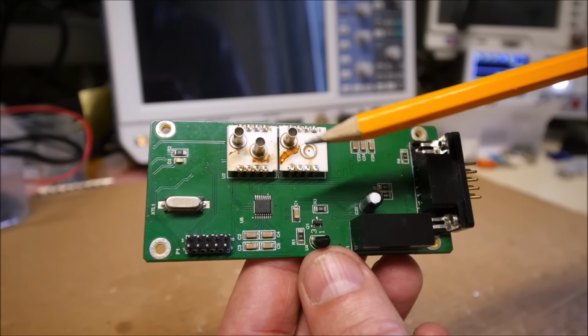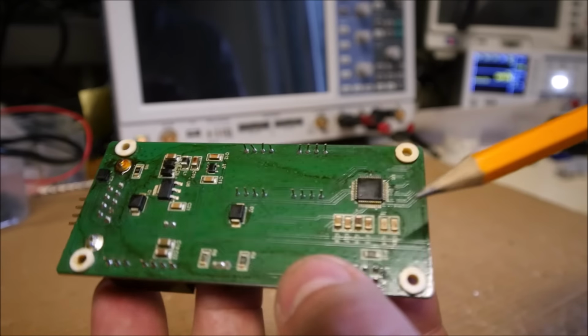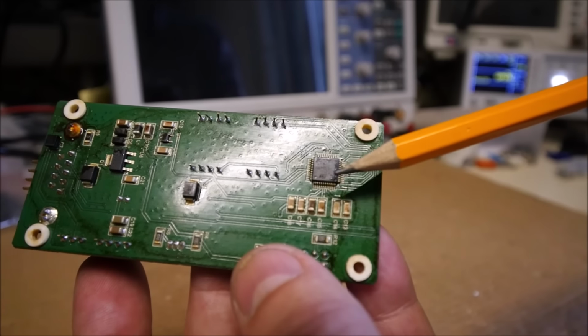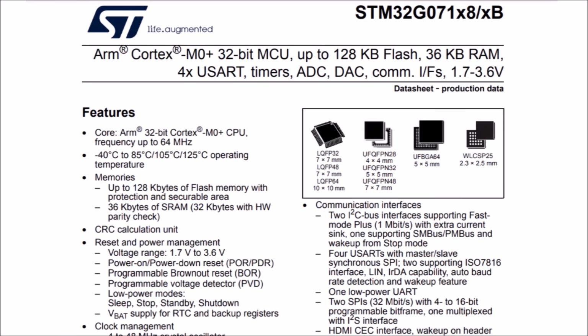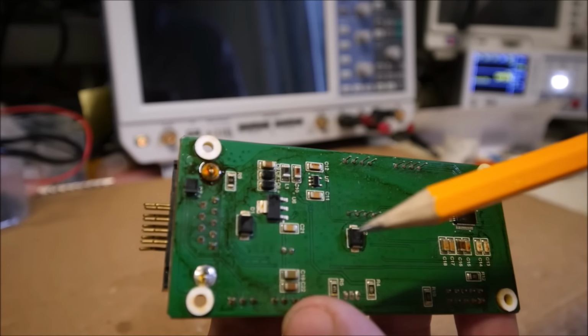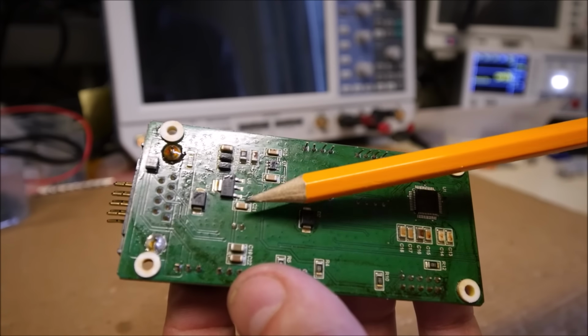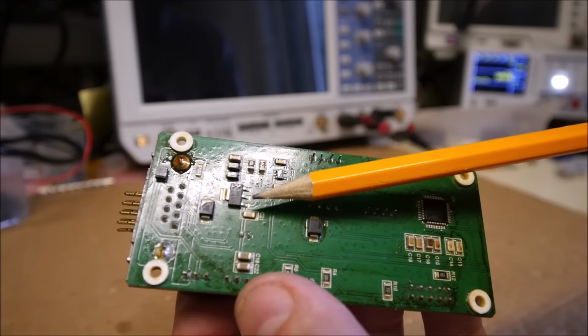There is here a small DC-DC converter, a sub-D9 connector here. We have here an AD3232, which permits the interface with an RS232 bus. Here there is a TO92 part, which is the classic TL431. On the other side, we have here a microcontroller, which is an STM32. There are some passive parts, a few diodes here. Here there is an SOT223 part. It is probably a regulator. So this is a JTAG interface for the programming of the microcontroller.